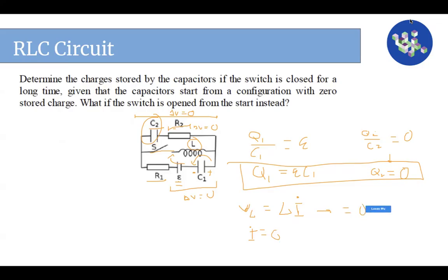So we can treat this branch over here as just a single wire. And that's really convenient, because what does that mean? If it's just a single wire over there, first off, if there was current, all the current would be flowing along that wire and there would be no current over here. Let me clarify that.